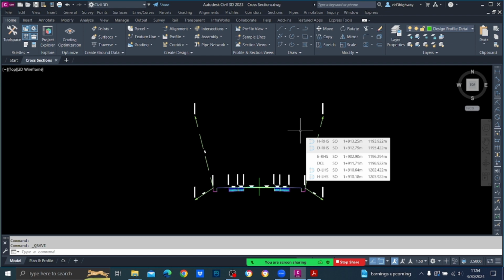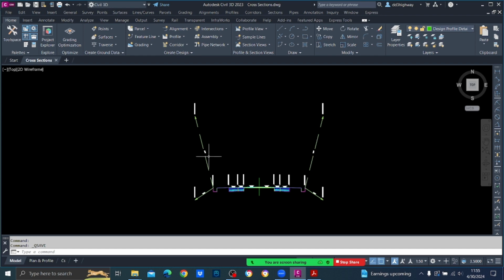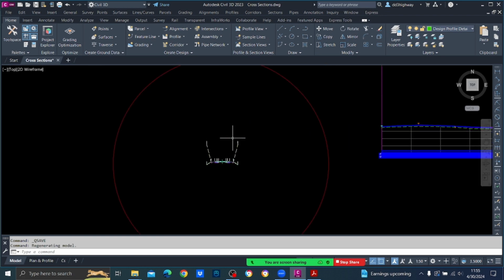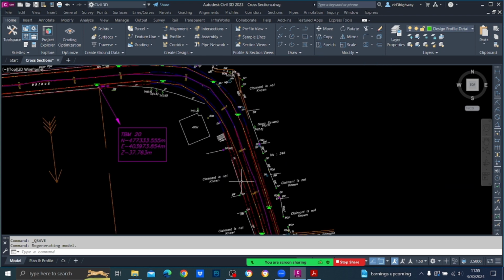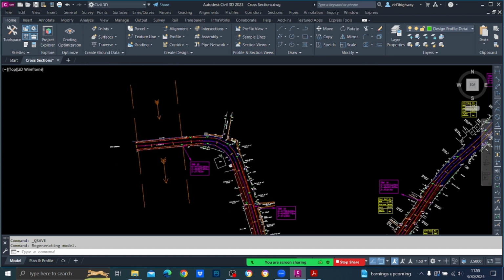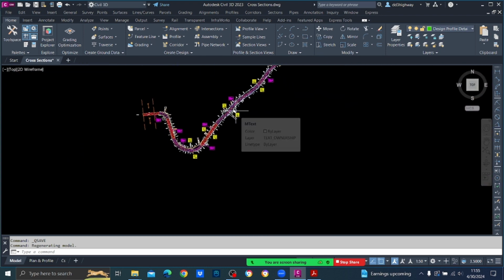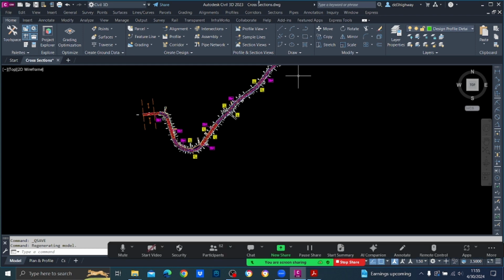Okay, right. Now we have to create the corridor. What do you mean by corridor? Corridor is we are running this cross section throughout this road. Okay, so now we will create the corridor. Now earlier also we created, that is the recambering corridor. Now we are running the final finish road corridor. Okay, so for that you go to corridors,